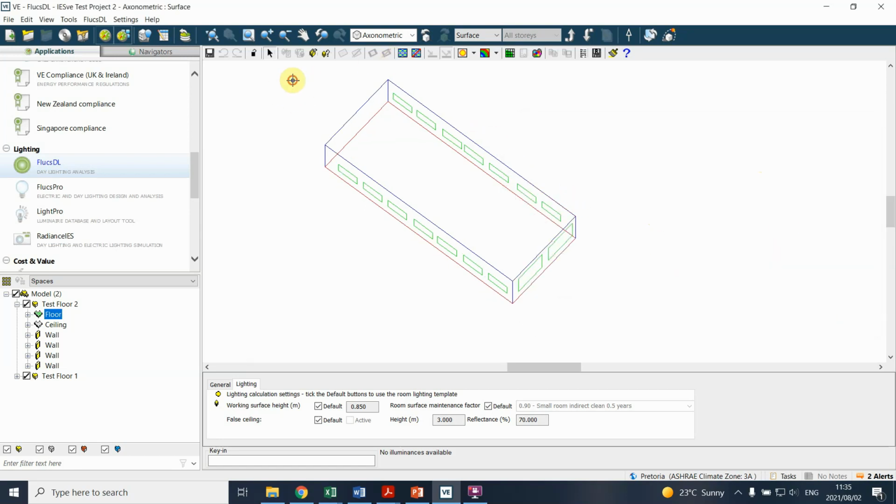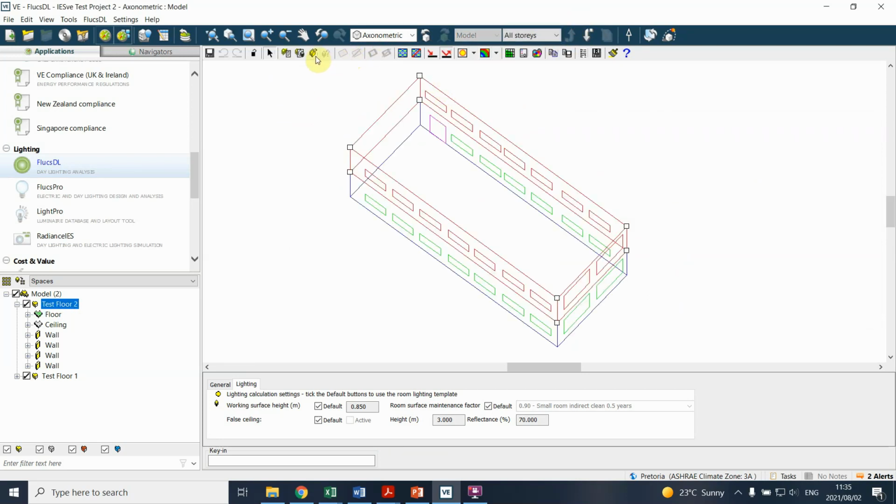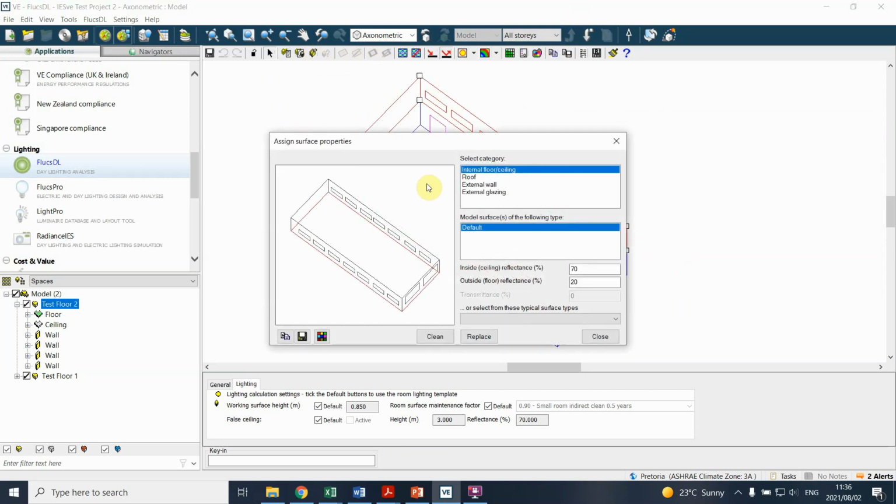Should you go and choose the whole building form itself, so we go up one step, then you can actually choose what the nature of the ceiling will be, what the nature of the roof would be, and so forth. And that's actually quite helpful. That helps you to assess. So obviously white walls can actually make a difference in the interior rather than black walls. As we all know, the reflectance and absorptivity makes a big difference.